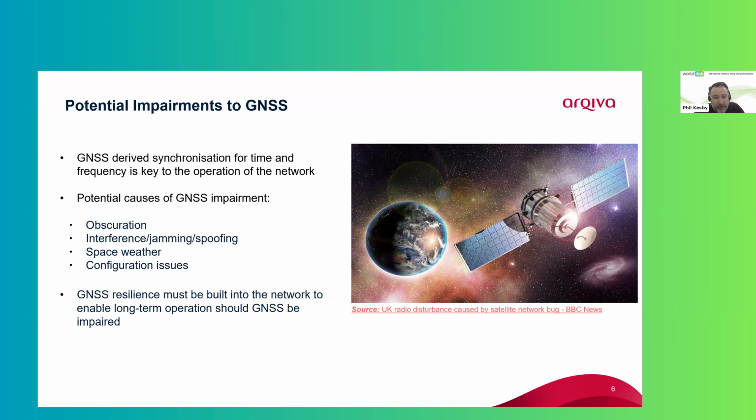But because the GPS and the GNSS signals are so low, around about minus 130 dBm, just low power jammers can cause you problems. But often we find in the UK that the jamming issues are short term. One mitigation approach that we found quite useful here is the use of good SAW filters.